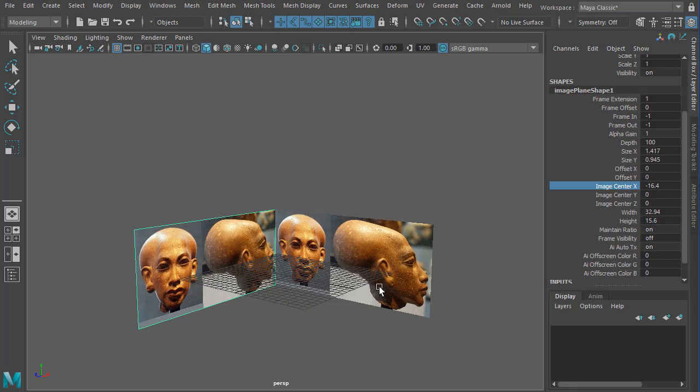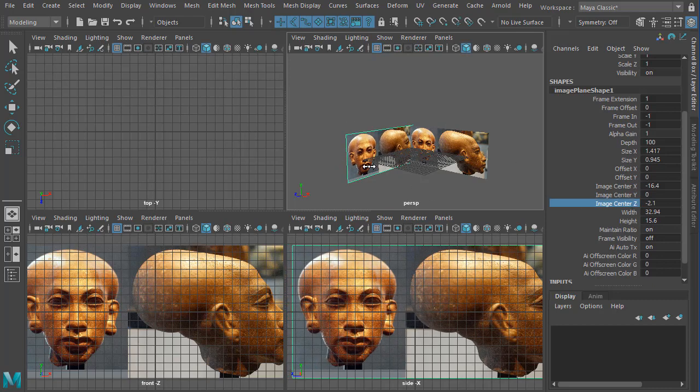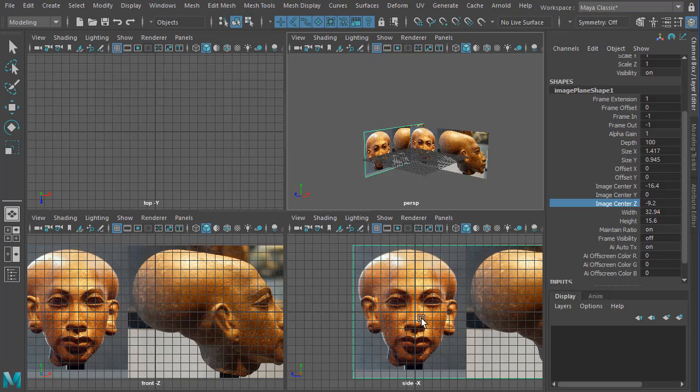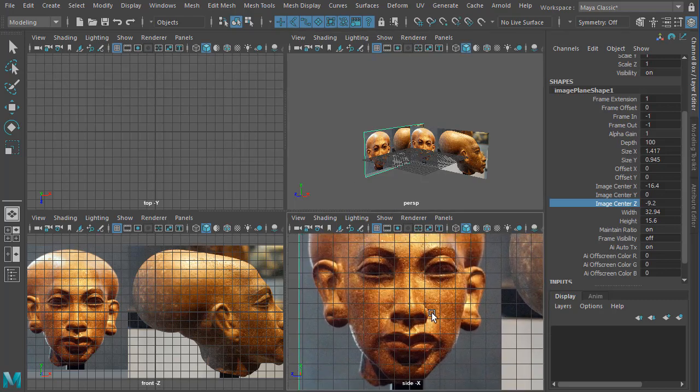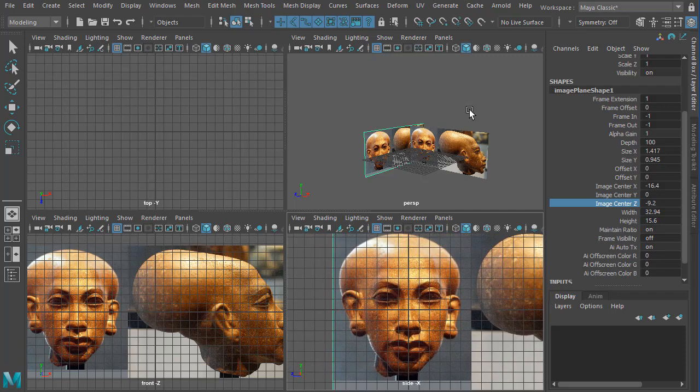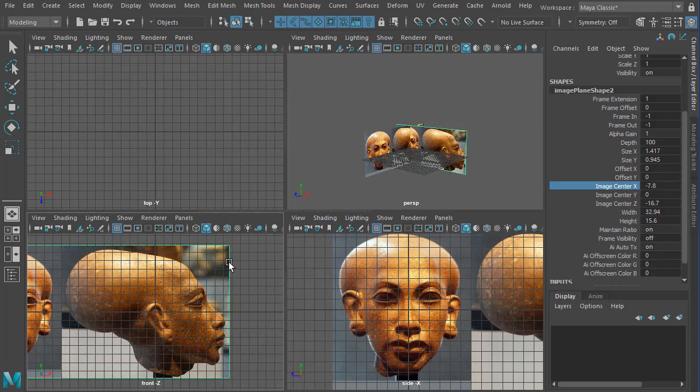Next, we can make sure that the views are matching up fine. In this case here, it has to be the front view. So let me just move that front view to the center. Here we can check that the middle of the nose or the mouth is actually on this grid line. That is perfect. I can do the same thing for this one to bring the ear area to the center. So let me just click on this x-axis and push it something like that.